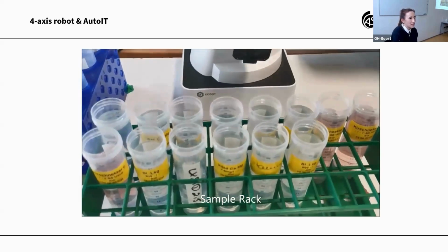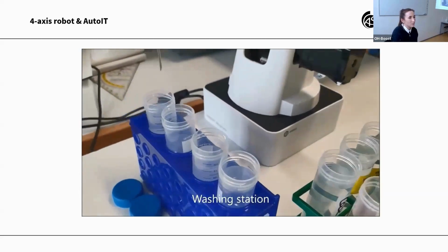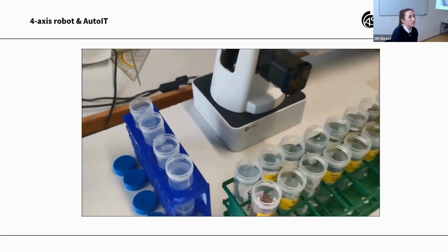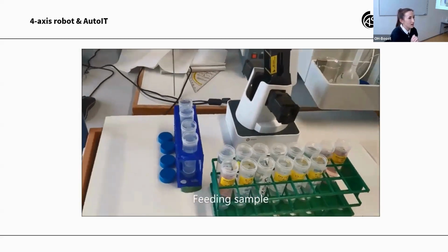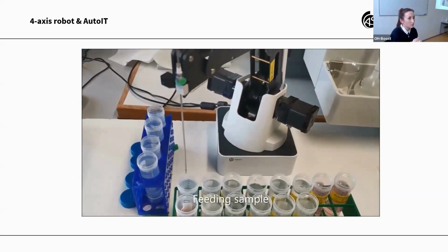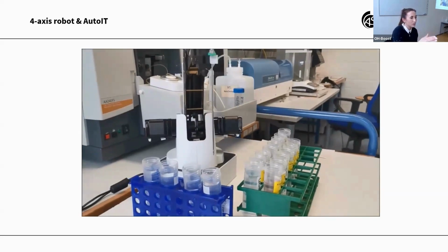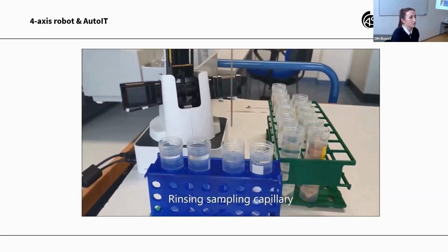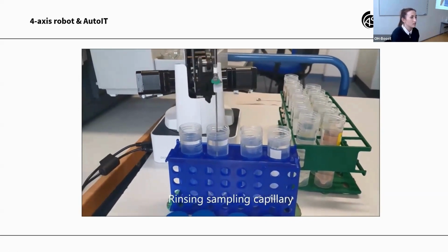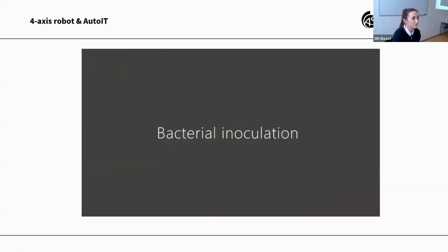Also, for the autosampler process, the personnel usually wipe the steel needle after it was in a sample, and here we had to implement a washing station because we were not able to automate this wiping process.